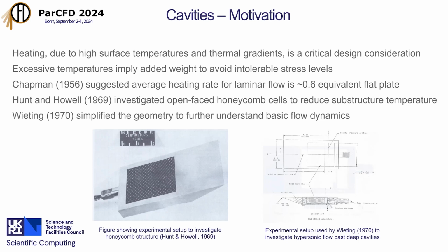There was a really famous fluid dynamicist, Dean Chapman. In 1956, he did a theoretical analysis of a cavity flow. He had to make lots of assumptions for doing it. But based on that, he demonstrated theoretically that you got about 60% of the heat transfer rate compared to a flat plate situation.